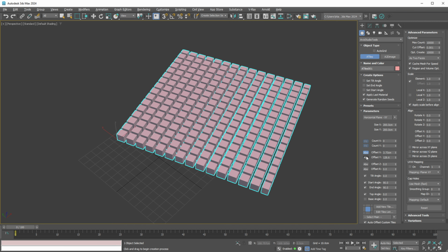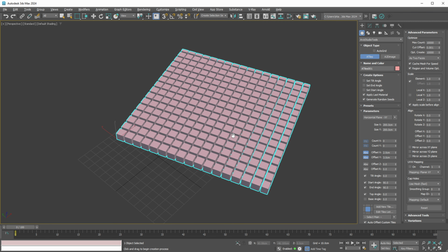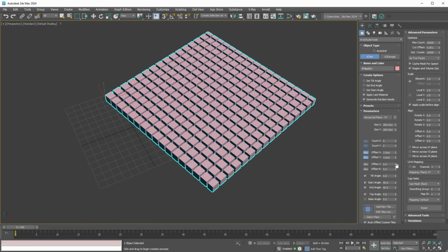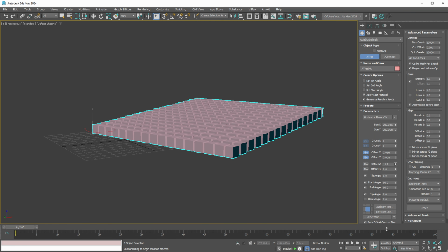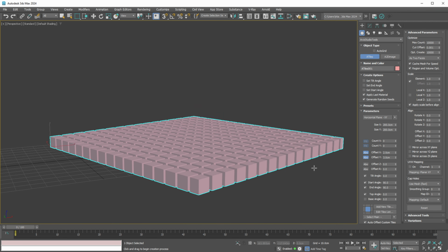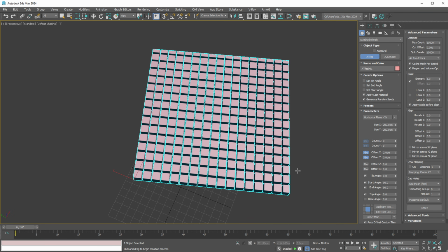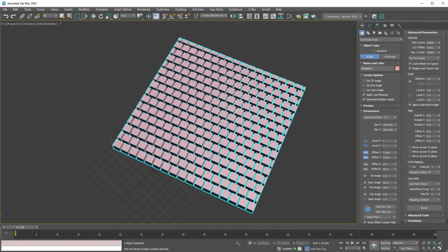You can also set it as an absolute value, defining the distance between tiles in system units. For instance, you can set the offset x to 2 cm and offset y to 3 cm between current tiles. Additionally, adjust the offset z to offset each row in the z direction to create objects such as step stairs or similar. The next offset R parameter shifts every second row by a specific percentage. For example, at 50%, this could be used to create patterns of brick walls or similar.